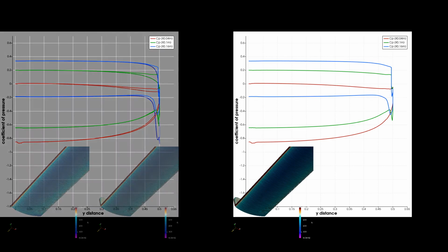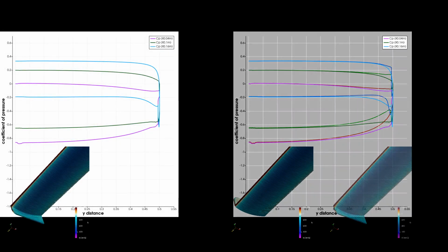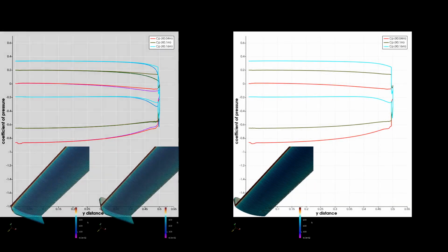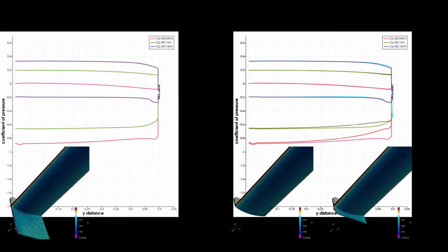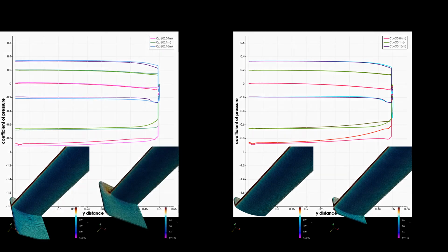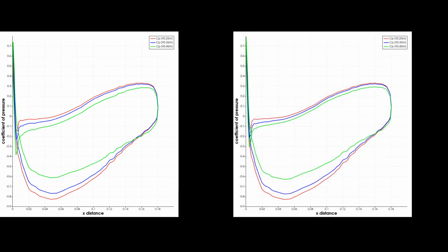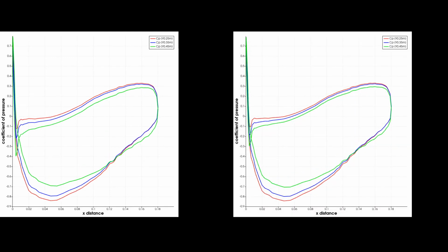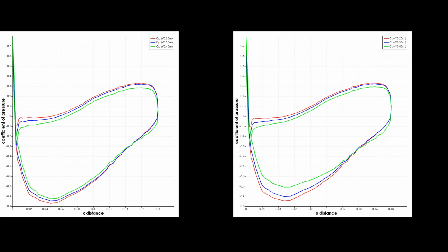The spanwise plots illustrate how the loss of pressure difference is reduced. All these overlays show how much improvement there is in increasing the pressure difference. As such, the lines slowly become straighter. Chordwise, the line plots at each point along the span become less different, therefore reducing the losses in downforce.